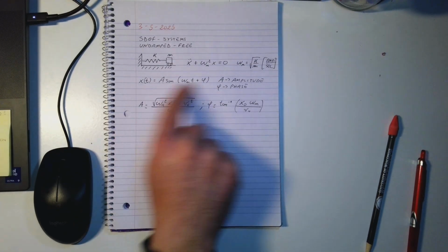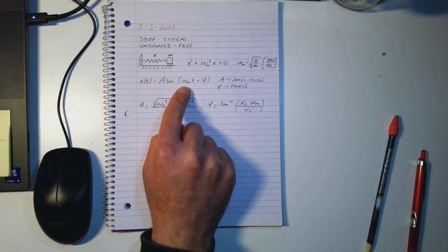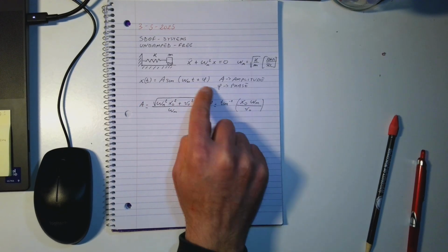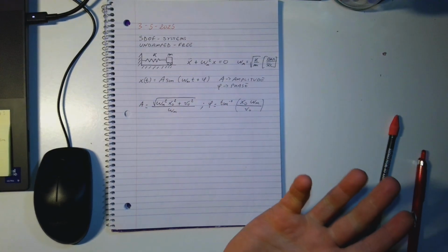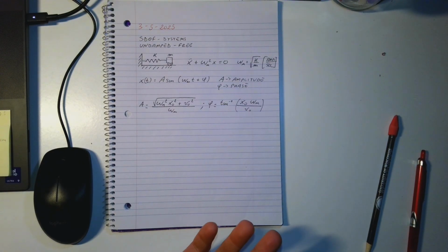So, of course, now we have the particular solution of our equation of motion, so we can plug this quantity here and this quantity here, and assuming that we have values of elastic constant, mass, initial position, and initial velocity, we can plot finally our displacement as a function of time.